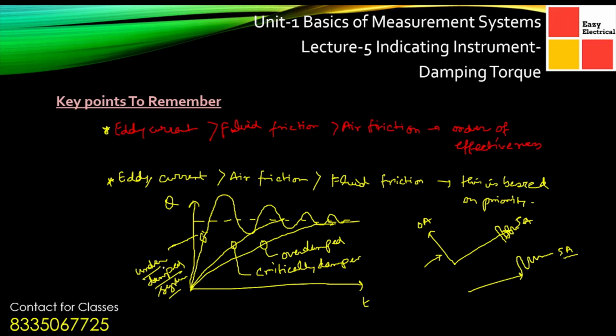One point I have mentioned here as well, that underdamped systems are what we basically prefer. Why we prefer them is because the pointer has some mass, and it produces inertia. Whenever we use critical damping, it is not good for the mechanical system, and underdamping is preferred so that the inertia dies out in the underdamped state. That is the reason why we use underdamping.